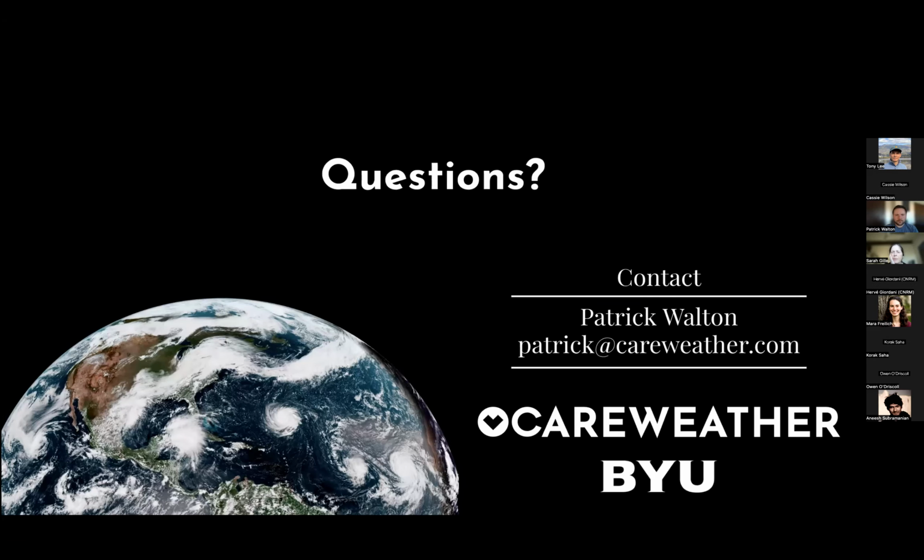Maybe I can ask, I guess I'm wondering about the design of a square flat satellite rather than a circular flat satellite. It seems like in something that spins, there might be a reason to have it sort of azimuthally consistent. We may find something along that realm. We haven't gotten quite that far down the path, but based on our work so far with the attitude control system, I don't anticipate a problem like that. I think the main difference between the circular and the square flat satellite designs has been designing to the launch slot. Those circular ones from Aerospace are designed to take advantage of the full cross section of a small launch vehicle, whereas we get more of a boxy slot that we can divide up in a SpaceX rideshare.